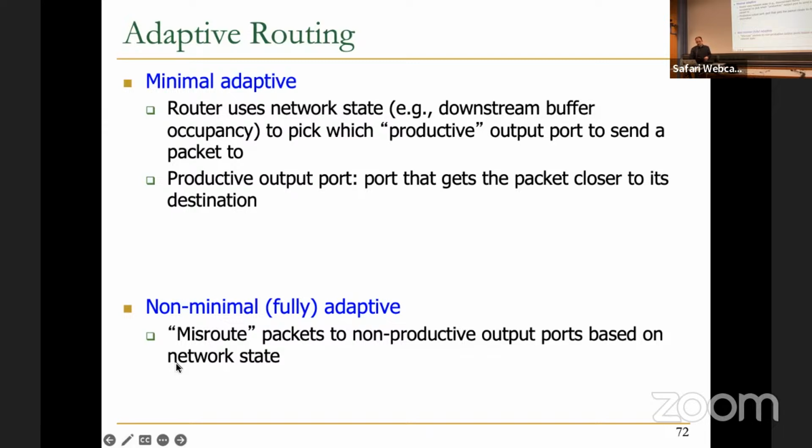One of the topics that you're going to see next week is when we want to design a bufferless NoC. When your network is bufferless, it means that you cannot wait, right? There is no buffer such that you can wait. So how do you handle conflicts? You have this idea of routing which we call hot potato. You get a hot potato and you just pass it to another one. You don't care who you are giving the potato to.